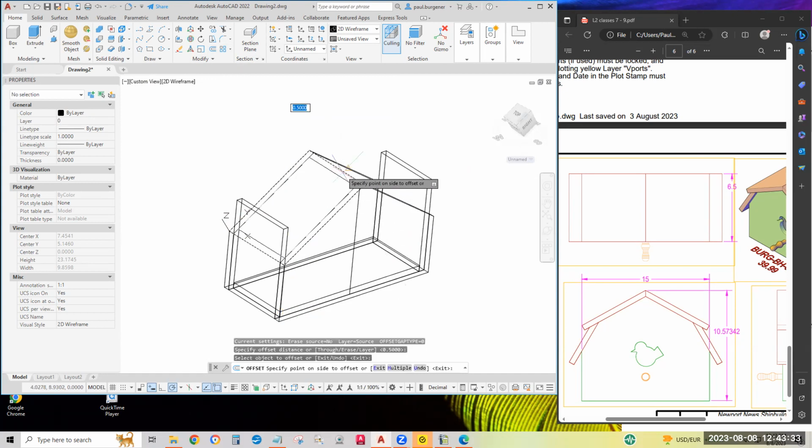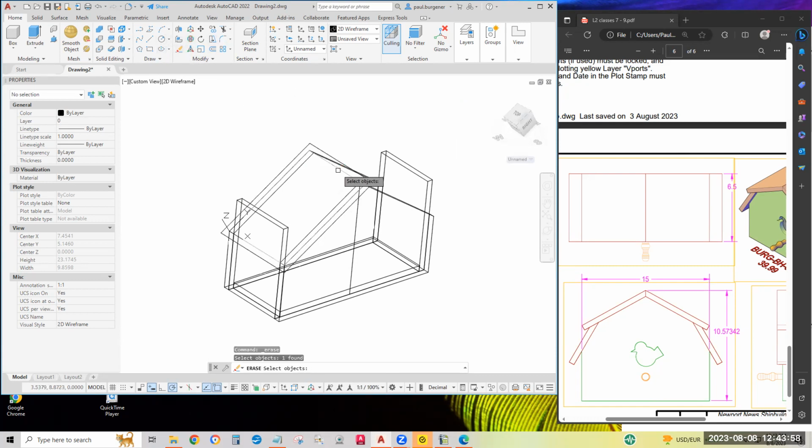I'll click the polyline and click outside the small rectangle. That's the part I forgot. Okay, we've got no use for the original polyline we drew on the temporary XY plane now that we've offset it out. So let's go ahead and erase it before it causes confusion.